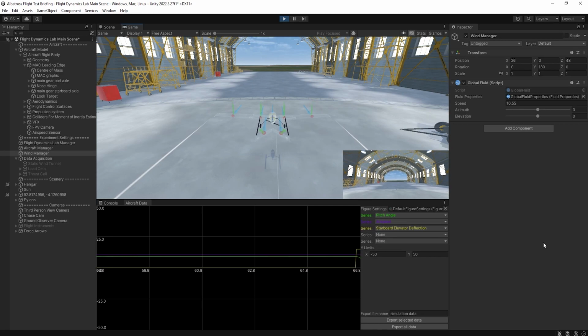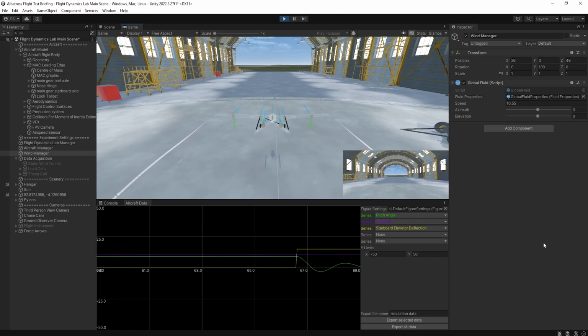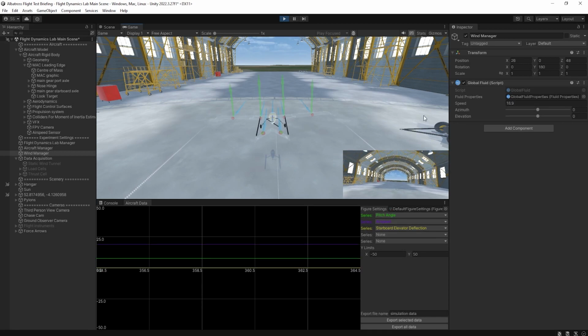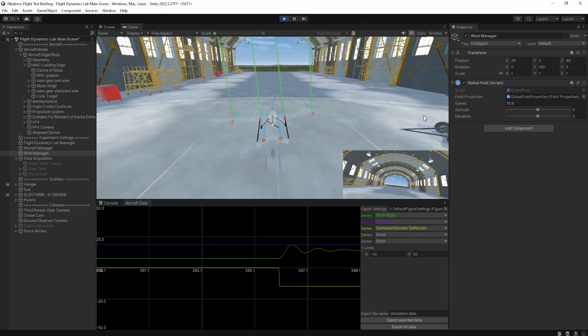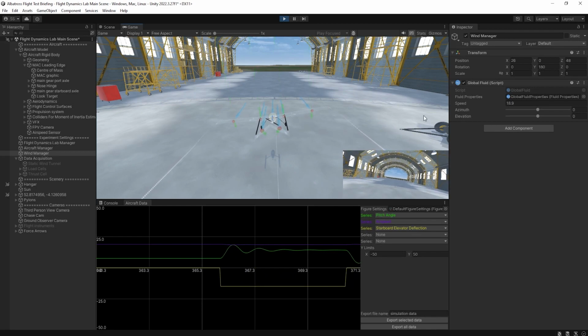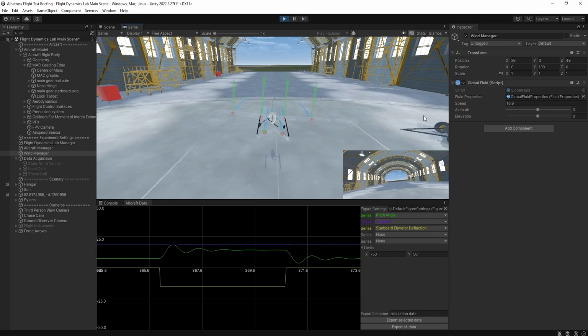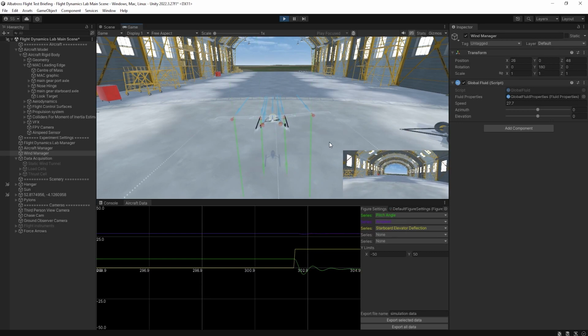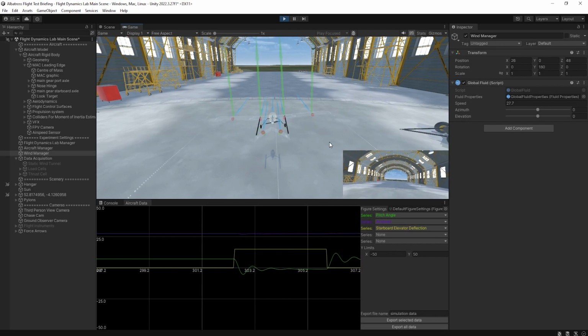These deflections were also made at different velocities, with the first being at the stall velocity of 10.5 meters per second. A slow pitch response is observed at this speed. The velocity was then increased to the cruise velocity of 18.9 meters per second. A fast response that decays quicker is observed. Upon increasing the airspeed to the aircraft's maximum flying speed of 27.7 meters per second, the fastest pitch response is observed, with a smaller short period and higher damping ratios.